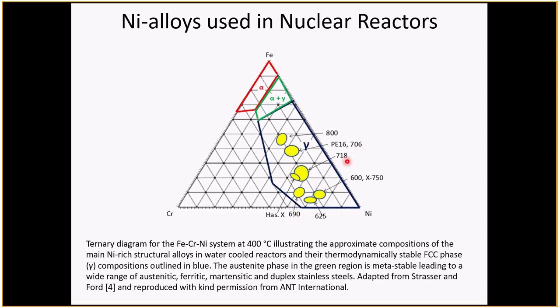These, 718 and X750, are used in springs, but also in other special components where high strength and high ductility are required. Alloy 600 has a composition very similar to X750, except it doesn't have enough titanium or aluminum to form the precipitates that X750 has. And we'll talk about these ordered precipitates, the gamma prime, and what gives some nickel alloys their precipitation properties, but